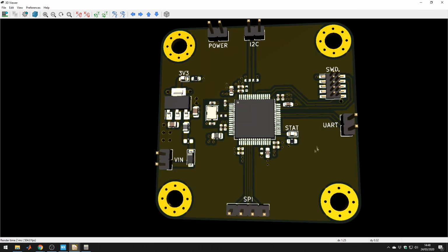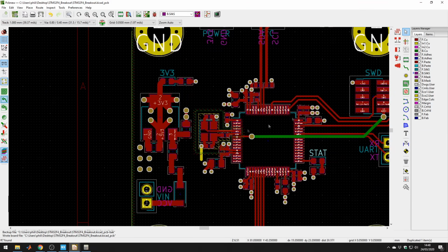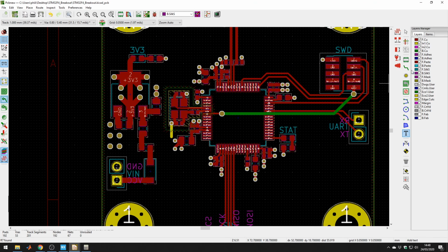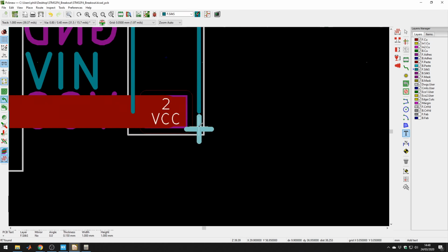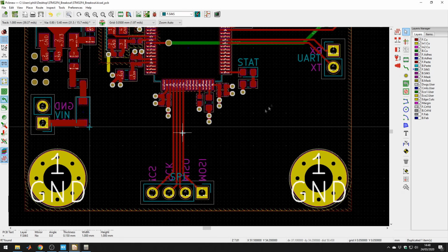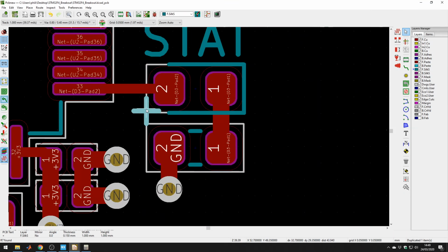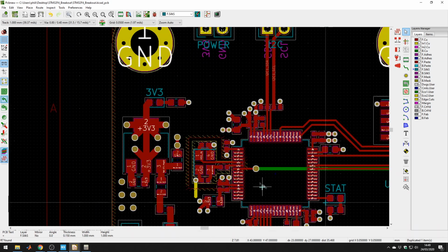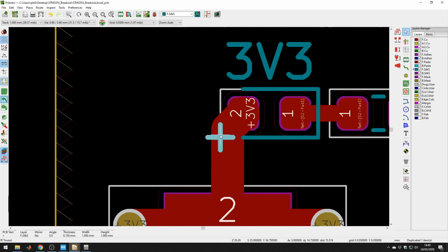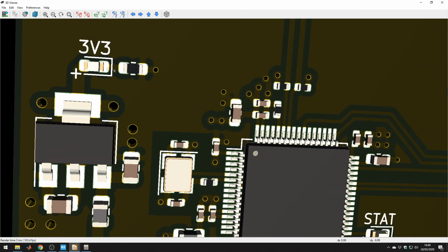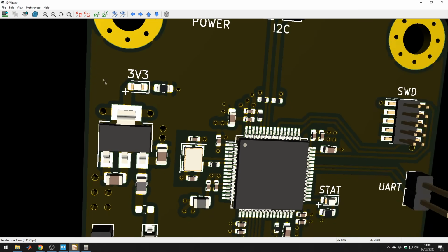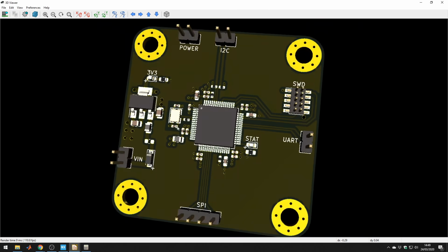But polarity for diodes, light emitting diodes, and this diode, let's put that on. I will do that just by front Silkscreen and just by doing a plus, as in for the anode. People might not like the plus, but this is the way I do it. And that is always a good thing I think to do. You have these little boxes around it to indicate the polarity, but I think this makes it very clear.